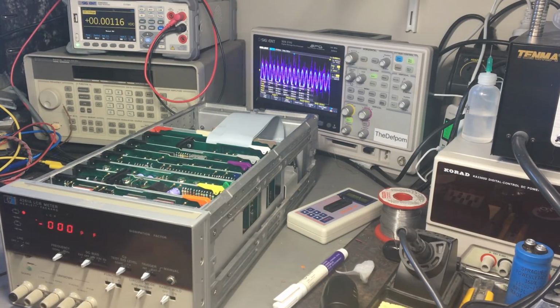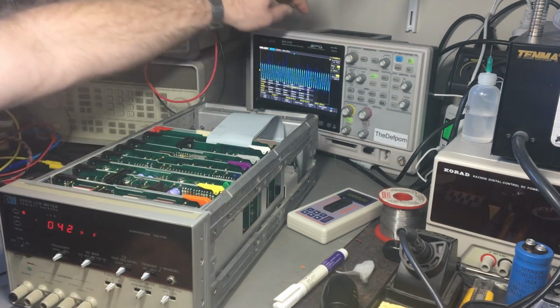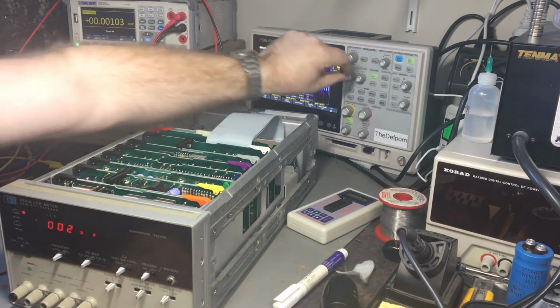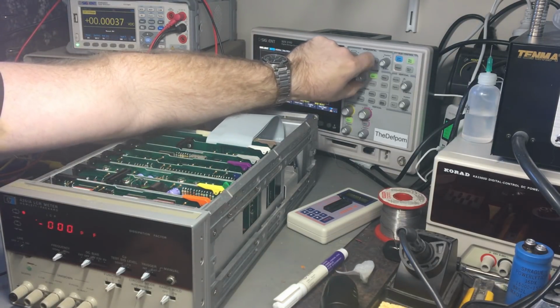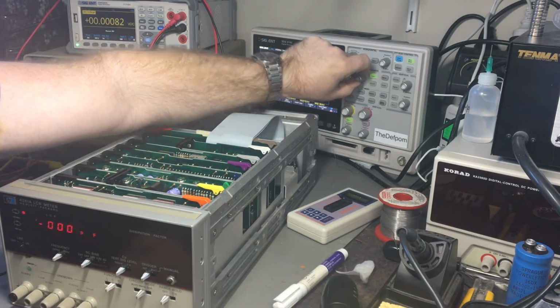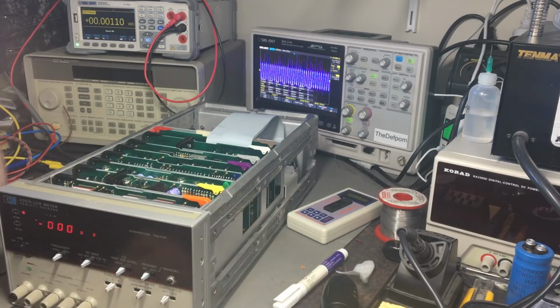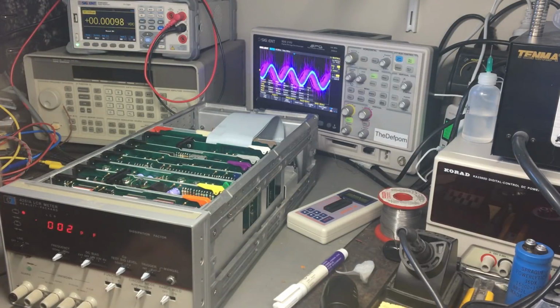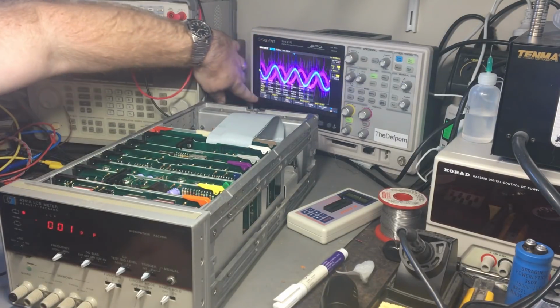So next thing I'll do is check whether the frequency changes when the frequency switch goes from 120 Hz to 1 kilohertz. Well, it's supposed to be 120 hertz, is it? Yeah, there's an awful lot of noise in there. The trigger's way off the screen. Let's bring the trigger down. So there's so much noise in there. Let's see if I can get that a bit cleaner.